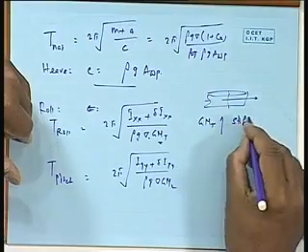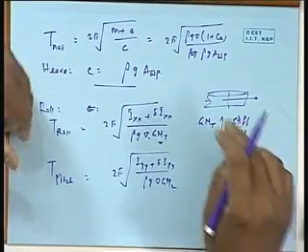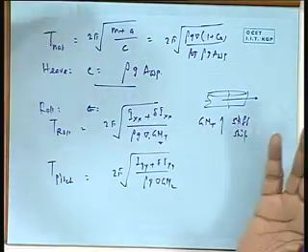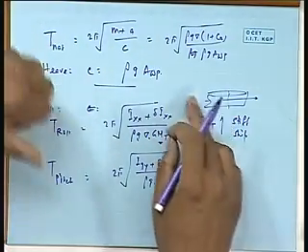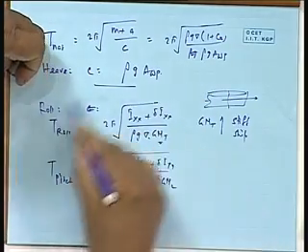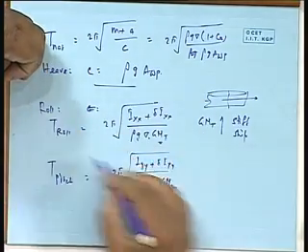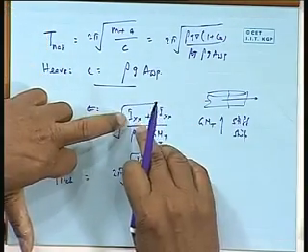A ship with high GMT is known as a stiff ship, and with low GMT it is called a soft ship. A stiff ship is more stable. So you have to make a compromise. We will not work it out, but you can work it out from these typical values, because it is easy to estimate.